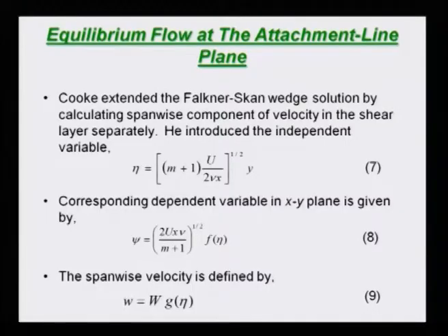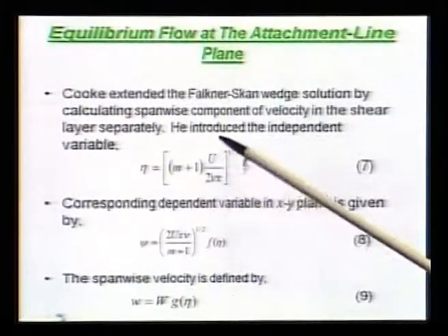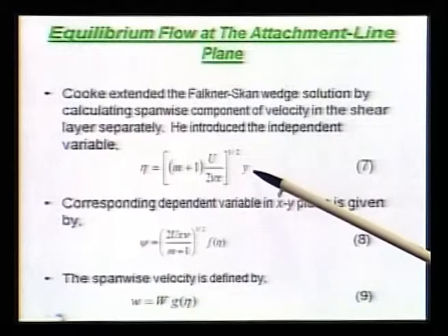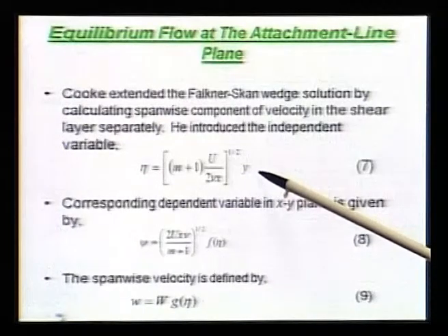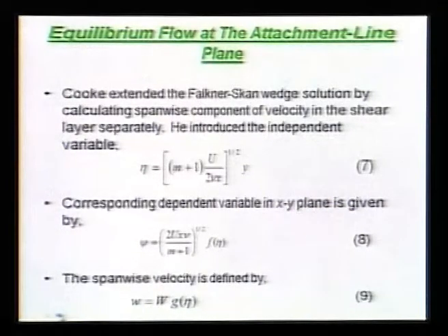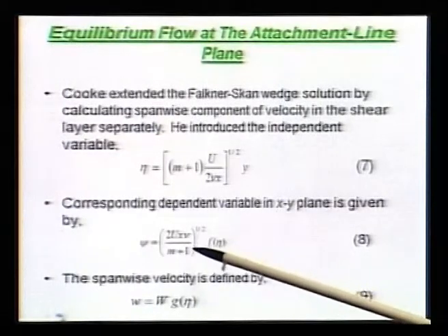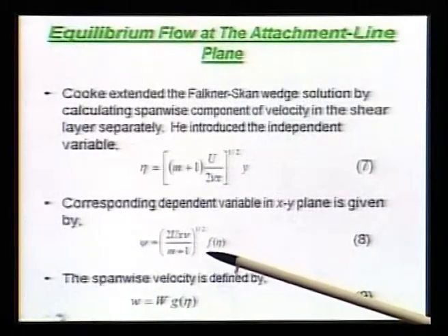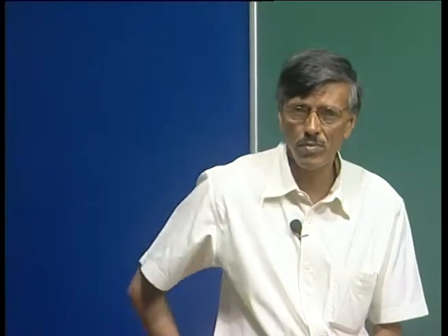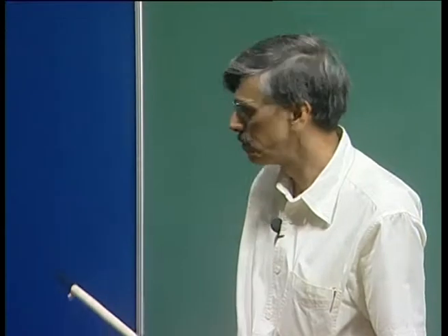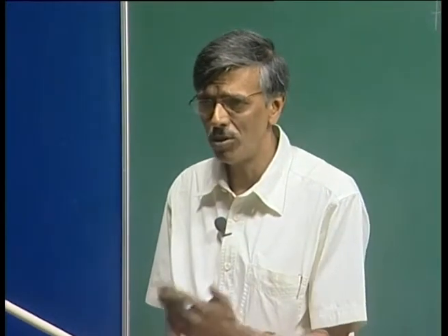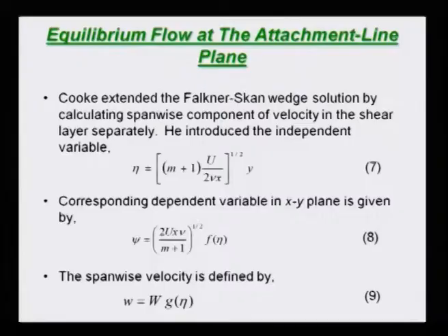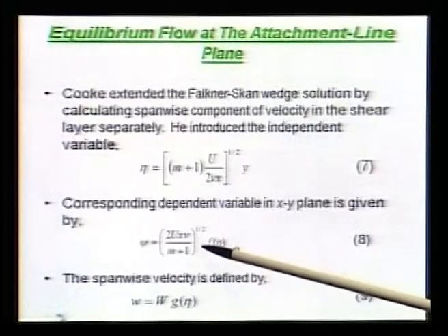So, that is what comes here, and you scale it by Re by square root of x kind of thing, and it is the y coordinate that is stretched. So, you are stretching that way. You also define a stream function. What is the idea here? Of course, when you introduce a stream function, then in the xy plane you do not need to worry about mass conservation, it is automatically satisfied. Existence of psi will give you that.